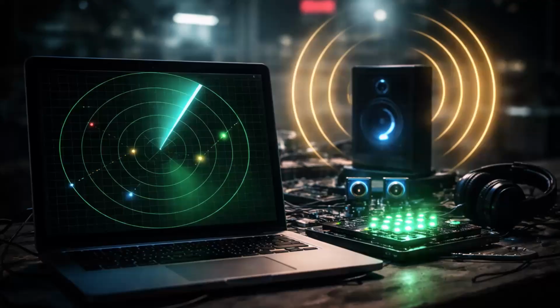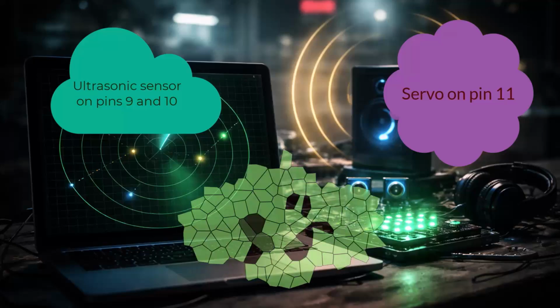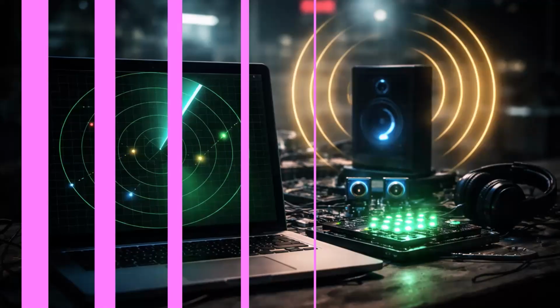The hardware is exactly the same as lesson number 7. So we have an ultrasonic sensor on pins number 9 and 10. We also have a servo on pin 11. We also have our 8x8 LED matrix on pins 12, 13, and 8, if you can remember, that we added in lesson number 7. The Arduino code is identical to lesson number 7. It just runs the servo, reads the sensor, lights the LED rings, and sends angle distance pairs, okay? Nothing to change there. So everything will just happen today in only the Python environment, okay?